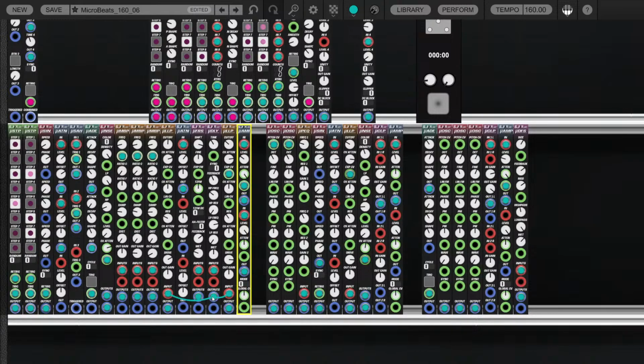From the delay we go into a low pass filter that is sequenced, that is modulated by an AD envelope, which is pretty interesting in my opinion, because usually you have a delay at the end of a signal chain, so you can have the delays ring out, the feedback feeds back and kind of prolongs the sound. But if you apply further processing that limits the dynamic range, like an amplifier or a filter, you apply that to the feedback, to the ringing out as well.